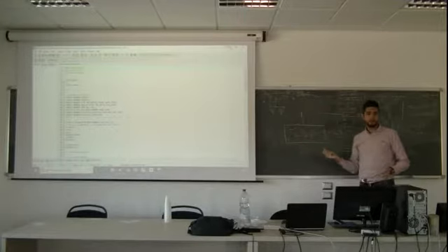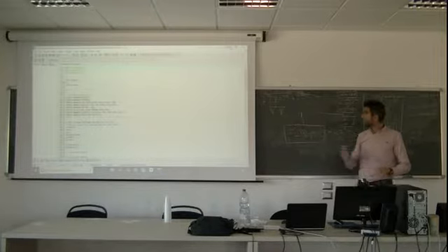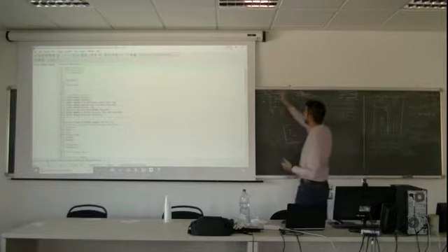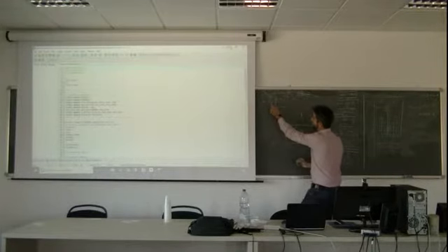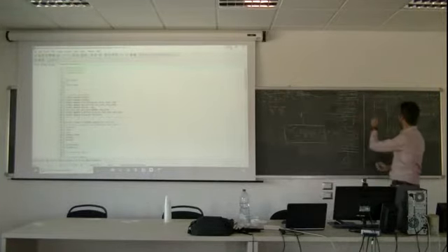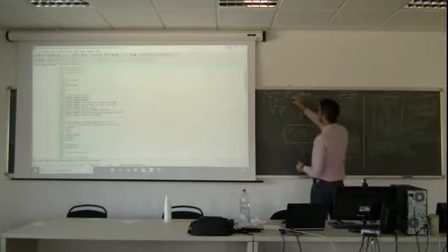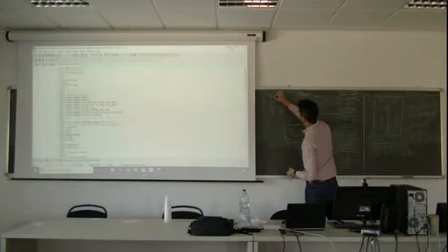Anything else happening in node n? Any more energy? There is the heat generated. Now, this part of the volume is generating heat at this rate, 500 watt per cubic meter. So we have QB.